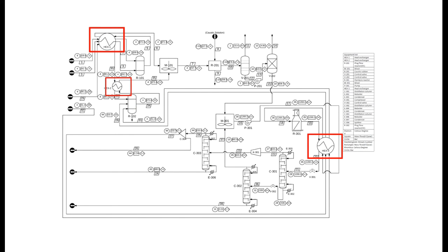Our calculations meant that we now needed 3 heat exchangers, 2 primarily found in the beginning of our process and 1 particularly around the distillation columns. This allowed hot streams to cool off colder streams rather than heating them up from the outlet temperature. Therefore, the energy consumption of our system is heavily decreased.